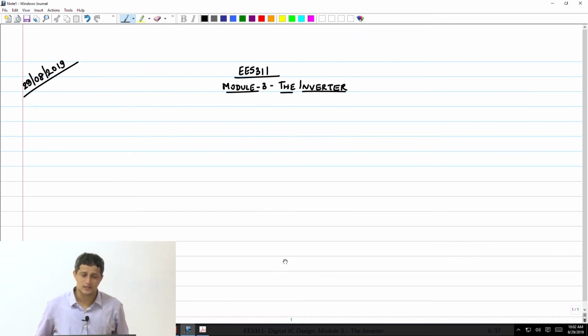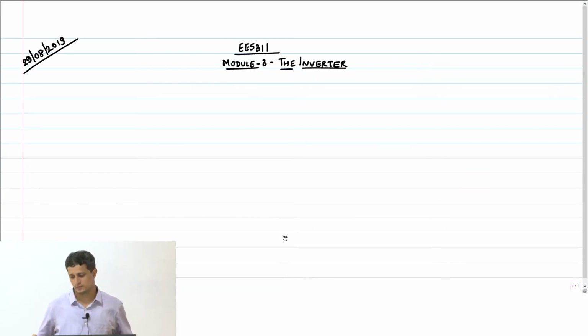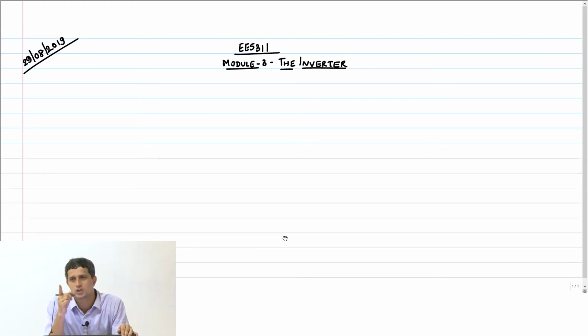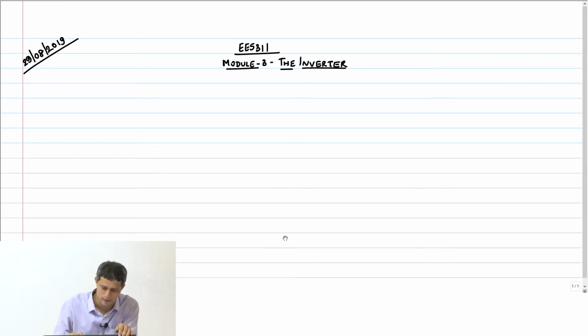Then we started discussing this switching threshold or the trip point, right. We were doing this analysis, and then after the class I realized that some of them were not very convinced with the argument I gave for why you should take the negative route, okay, when we considered the case of long channel devices. So what I'll do is, just for the benefit of doubt, I will go through the long channel derivation once more because that was done towards the end and maybe it was done in a slight hurry, okay. So let's just consider